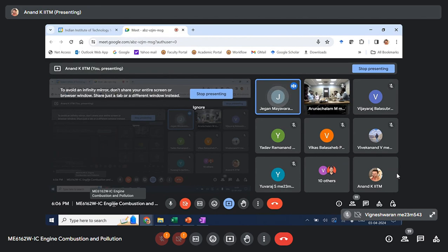But my only question was, sir, why are we taking exact TDC here? Maybe it's because of slow speed engines, sir. Because in generator engines, we don't have this. In generator engines, we have exactly what you said, sir, that we take the compression TDC only. But only for large 2-stroke engines, we have it like this. Large 2-stroke engine, your question is, we are taking 2 references, do we have to take them or not? Is that your question? No, sir. For large 2-stroke engines, I'm asking why we are taking the piston's actual TDC, not the compression TDC.